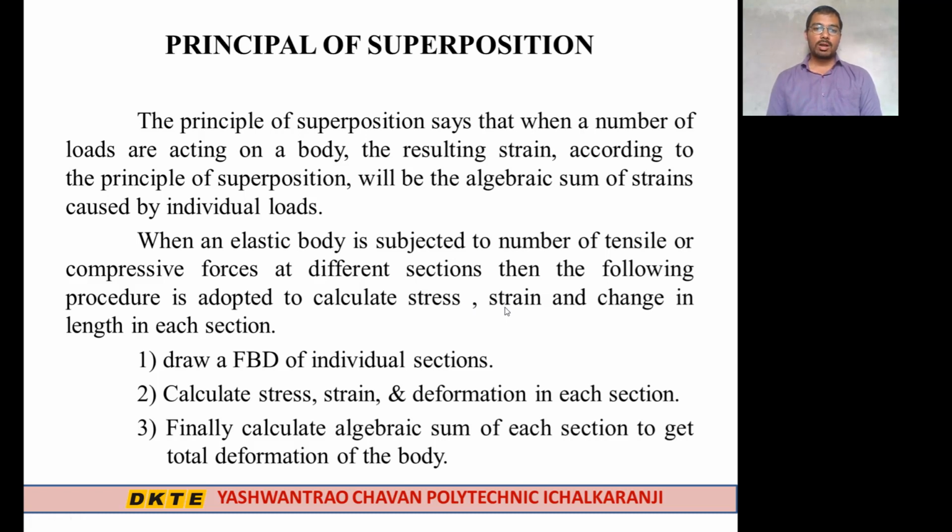First step is to draw a free body diagram of each individual section. It means we have to draw a free body diagram of each section and calculate the load acting on each section. Second step is to calculate stress, strain and deformation in each section.